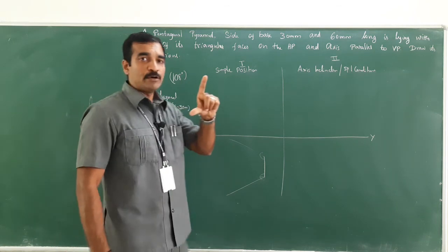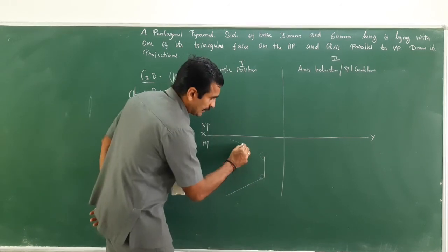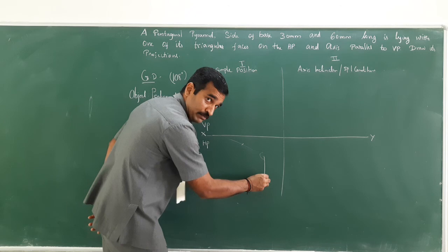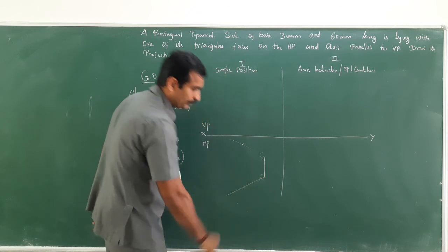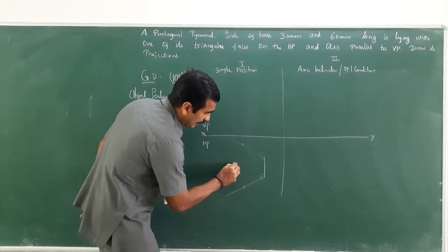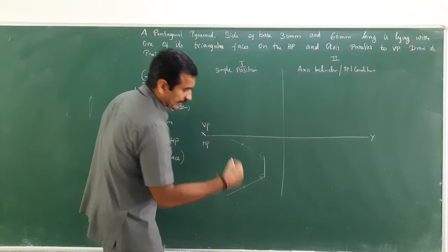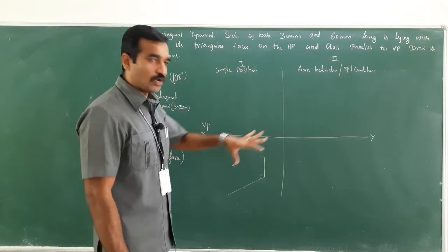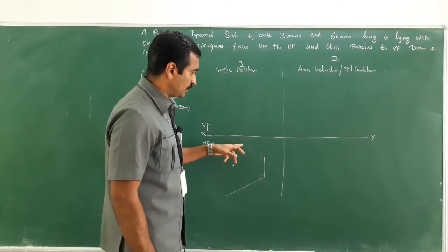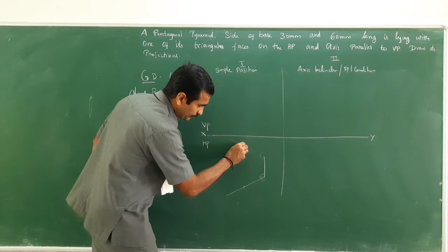Now take 30 mm in your compass. Keeping at the extreme point, cut an arc. Similarly, keeping at the extreme below, cut an arc. Now without changing the radius, keep it in the intersection point and cut an arc. Similarly, keeping at the intersection point, cut an arc. Now connect all the intersection points, or the arc which has been cut on the extension line. So now draw it.